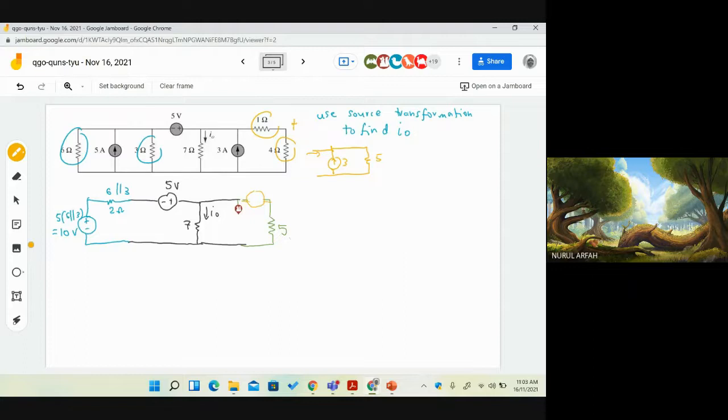But the direction, where is the direction? If you are unsure which is which, you can redraw it like this, right? And this is the current source going up. When you want to transform, this becomes a resistor and this is a voltage. But how do you put the current direction? Yes, this is correct. For those who are unsure which to put, positive first or negative first, you look at the arrow.